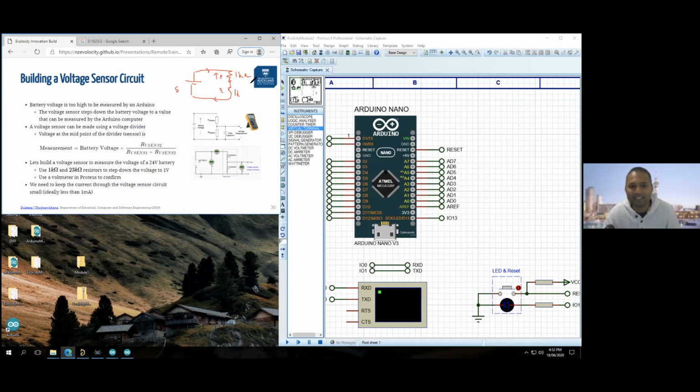And since the 2 voltages have to add up to 5 volts, we know that if this is V, this has to be V because the energy is the same. So we know that this and this have to add up to 5 volts. Yeah. That's the basic rule of a closed circuit. So if this is V, and this is 5 volts, then 5 volts has to equal 2V, therefore V has to be 2.5 volts.